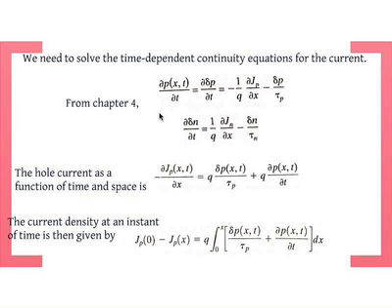The carriers are diffusing, going from high concentration to low concentration, electrons or holes, depending on which side you are. They are recombining: electrons are recombining with holes, and holes are recombining with electrons. The third thing is that carriers are being injected, or not. If it's reverse bias, they're not injected. But if it's forward bias, they're injected. There are only three things happening.